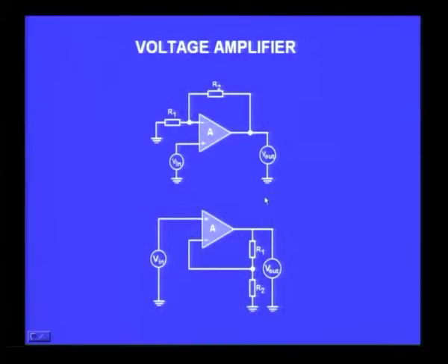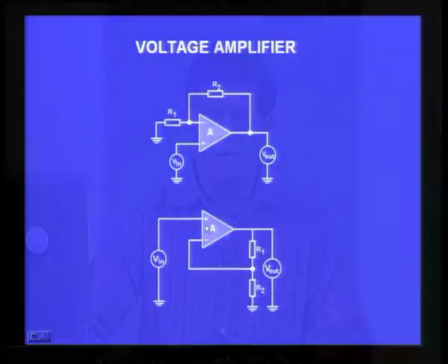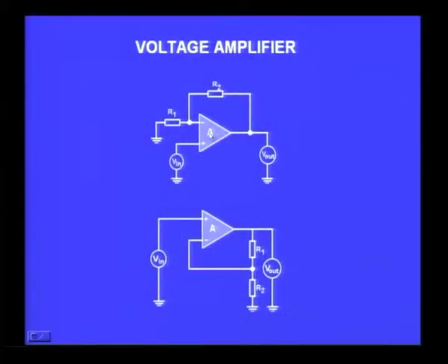You also should recognize that people tend to write circuits in different ways, show in different ways, but you must be able to recognize that they are of the same configuration. For example, these two circuits that I have shown on the screen appear as though they are two different circuits, but if you carefully observe, they are two identical circuits. You can see that the negative end is actually used for the feedback, R2 and the R1 is connected to ground. Therefore, this is R2 plus R1 which is connected in the feedback loop, and that is connected to the negative point. Therefore, there is a negative feedback.